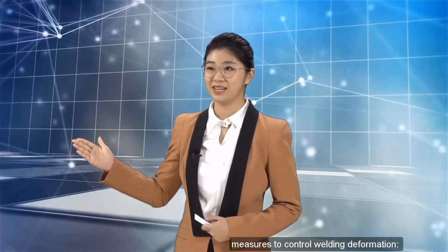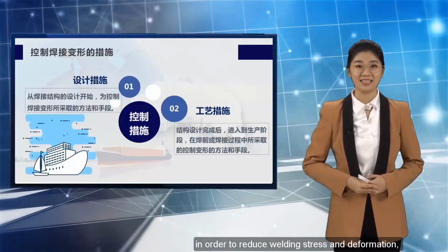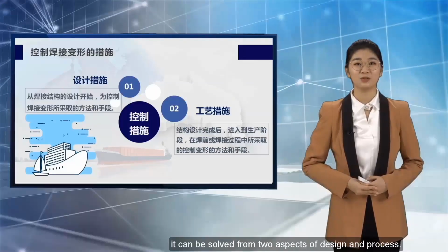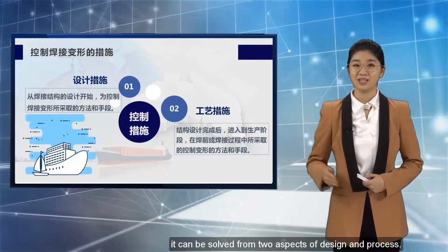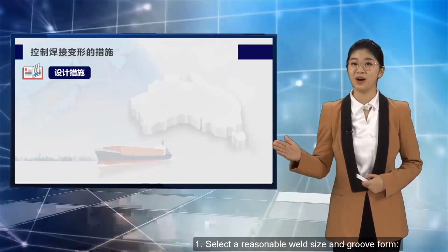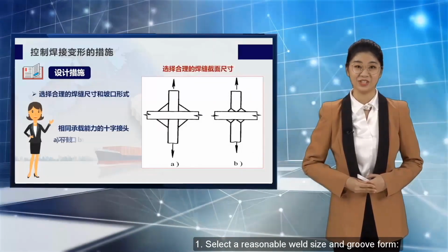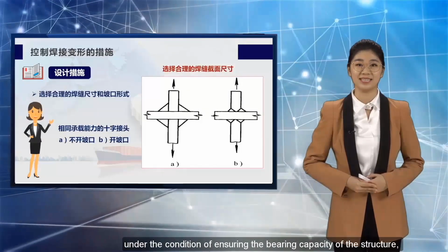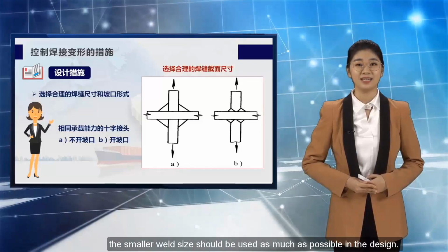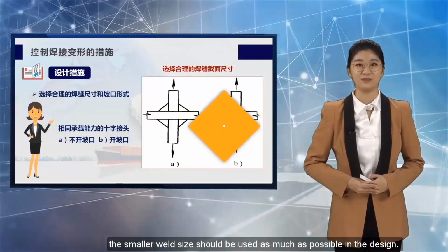The second part, measures to control welding deformation. In order to reduce welding stress and deformation, it can be solved from two aspects of design and process. Design measures. 1. Select a reasonable weld size and groove form. Generally, under the condition of ensuring the bearing capacity of the structure, the smaller weld size should be used as much as possible in the design.